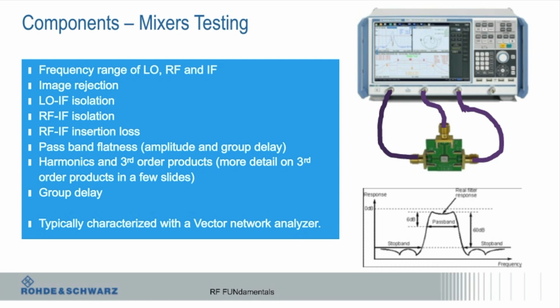So I'm going to go from 700 to 70. Can I do an RF minus LO, or should I do something else? When you pick the LO frequencies, you want to know all the extra junk that gets through, whether it's going to be a problem, and whether you can filter it out, because you're going to have a filter in here somewhere.